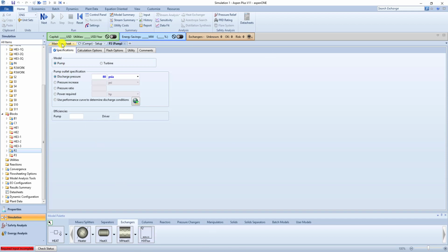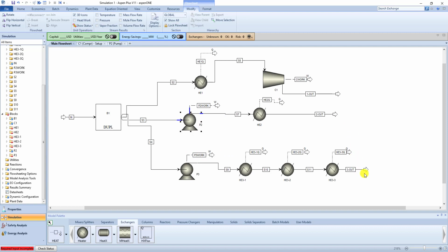Similarly, for pump 3, if we work backwards, so if heat exchanger 2 is vaporizing, and we don't have any change in pressure through there, for a boiling system there will be a pressure drop. However, it's negligible, or we're going to neglect it for now, which means that we have our 5 psi drop roughly through heat exchanger 3, and we have a 5 psi drop through heat exchanger number 1.